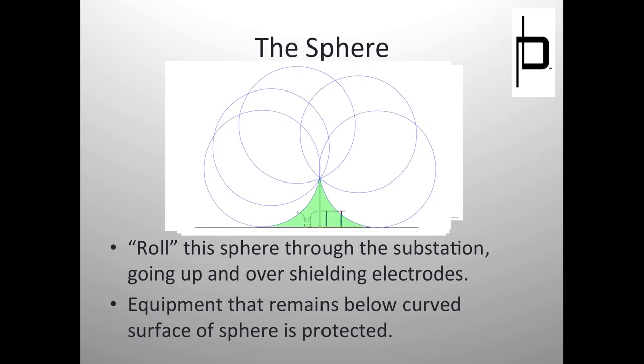And items that fall inside this area, under the sphere, are considered protected. Okay. Items that fall outside this area, or within the sphere, are considered to be exposed. Right? This, for example, this piece of bus, let's say you have a step leader forming at this red X. Let's assume this red X is the center of this circle. This is a step leader forming. This circle represents the strike distance, the items that are within reach of a step leader forming here.